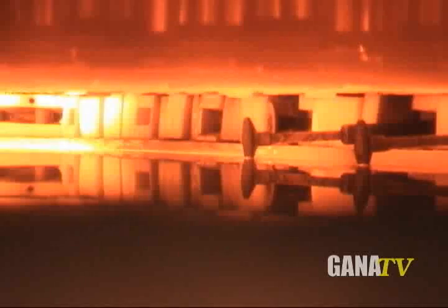Natural gas and superheated air raise the batch temperature to 2900 degrees Fahrenheit, at which it melts. Once melted, glass leaves the conditioning zone at a temperature of about 1900 degrees Fahrenheit through a narrow canal where it flows onto a bath of molten tin, which has a higher density than molten glass.